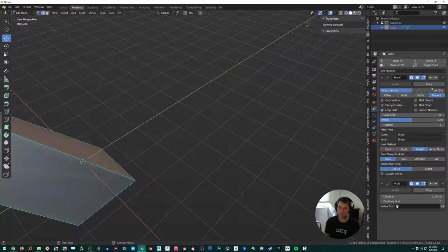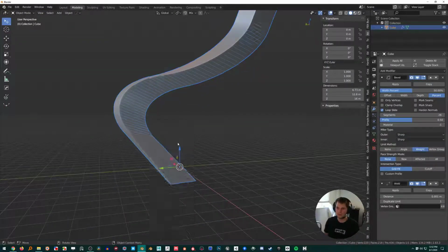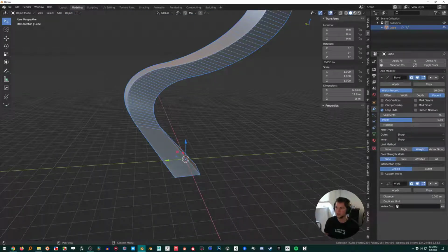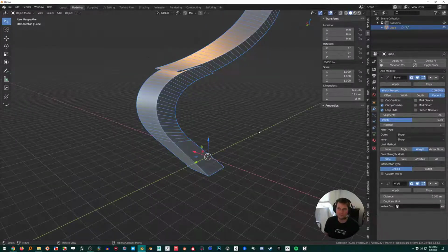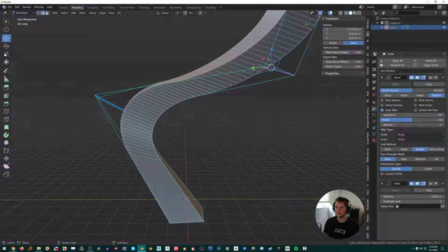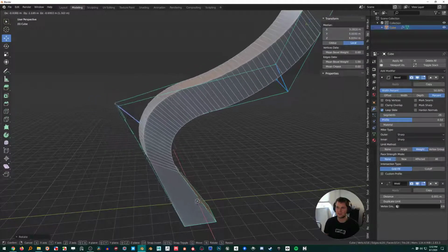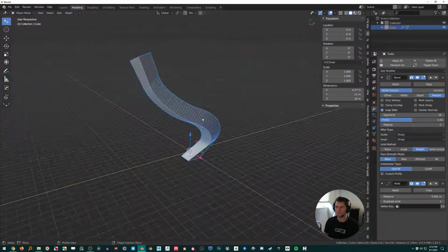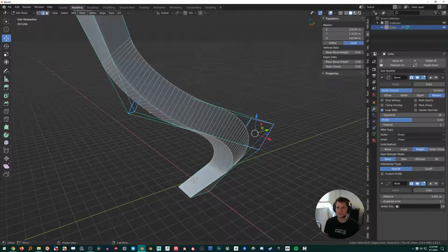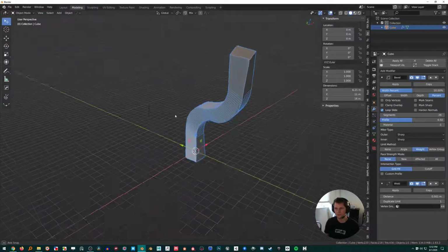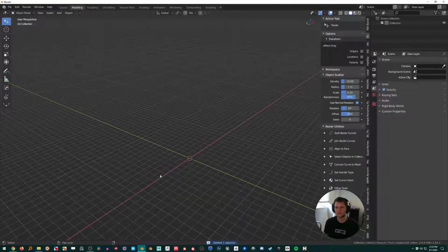Okay, so then we have this 50% thing. The drawback to this is that it's only going 50%, so you're not going to get this whole thing here. If I put on 100% and clamp overlap, it's not good. Just turn clamp overlap off, and you're going to get the results you want. So this is a really nice method. It behaves kind of like Bezier curves or subdivision modeling. The nice thing about using this method is that you have so much non-destructive control of your curvature. I'll show you a real use case scenario where I needed this.